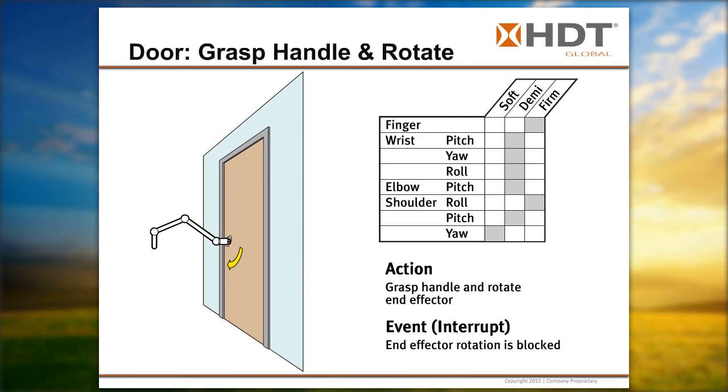And I can soften up pretty much everything because now, gosh, this is where things get really hard, right? You've got this rotation out in 3D space, and to try to figure all that out with eigenvectors and all you could go crazy trying to, but you don't have to. All you have to do is generally command that rotation of the end effector, and the slop is taken care of by the impedance control, by the ability to make things soft.